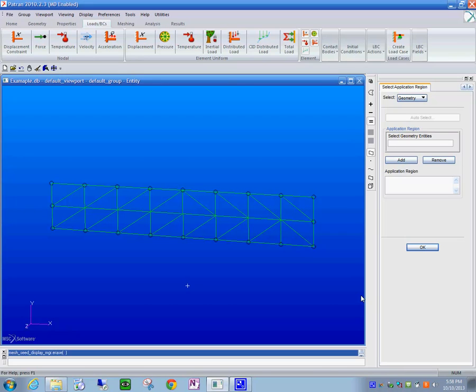So it doesn't make sense to keep it on the geometry, but rather see where it says Finite Element Model, do that. And then in here it says selected nodes, because if we kept it on geometry, it says selected geometry entity. What we want is the Finite Element Model, because we want to fix this node. See right there? Okay, I selected that node, and you say OK.